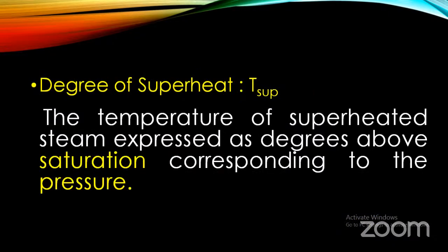And this is another temperature termed the degree of superheat. So beyond the dry steam, if you are going to add heat, whatever may be the heat added, it is spent in raising the dry steam into the superheated steam. So how much heat you are going to give in, that you call the degree of superheat.